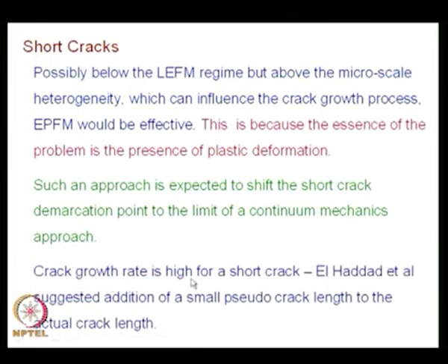Crack growth rate is high for a short crack. So, it is well documented in the literature. People have found that whatever fatigue crack growth theories we have developed are not applicable to short cracks because they have a higher growth rate. And people are accustomed to doing certain things in LEFM, so they extend similar ideas to handle this situation also.